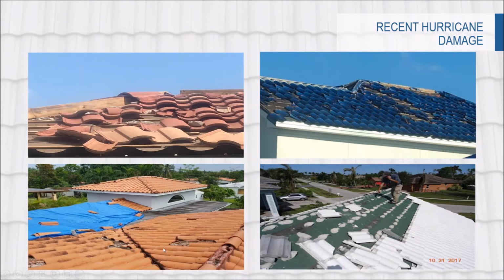In 2006, they enacted a metal or a wood member along these hip and ridges, and those projects that had that wood member or metal member along the hip and ridges were less likely to cause damage. So these trainings are very important to understand the proper application and really what works during these events. This right photo there, that's that mud set system that exposed Hurricane Andrew to a lot of the damage. These are mortar set patties with concrete tile.